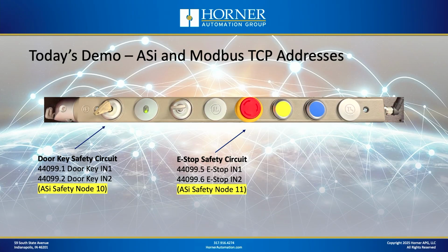Before we continue on with our demonstrations today, I just wanted to have a couple of slides where I summarized basically the data, if you will, that is available from the tGard, both from an ASi standpoint as well as from an ASi address standpoint, as well as from a Modbus TCP holding register standpoint. So if you're trying to do this integration yourself and using this video as an aid, you can see specifically which ASi nodes and which Modbus TCP holding registers I used in this particular demo.